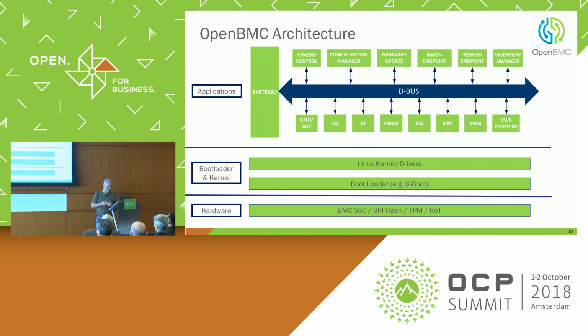It's the video controller, the ARM management controller, and the Super I/O chip with all the USB, video and network driver stuff. And I put in there the TPM and some kind of root of trust, which is the hint to Cerberus or Titan or Intel's version of platform firmware resilience. We're using U-Boot, of course, to start up, and the Intel implementations will have a secure boot implementation with signed images and signed firmware updates that will be made available as well.